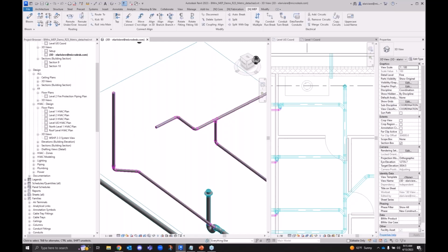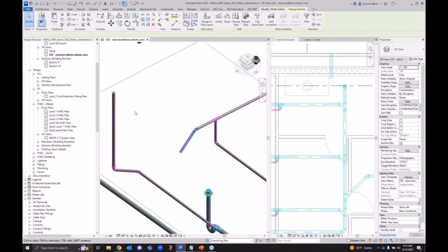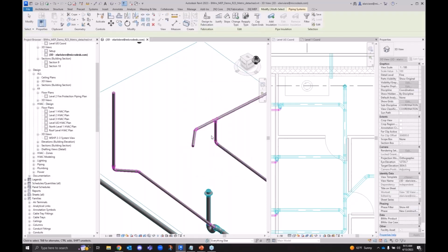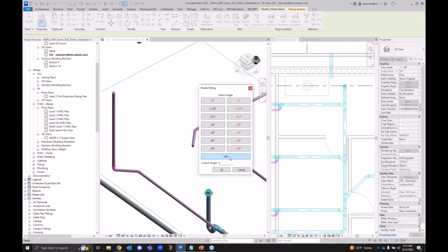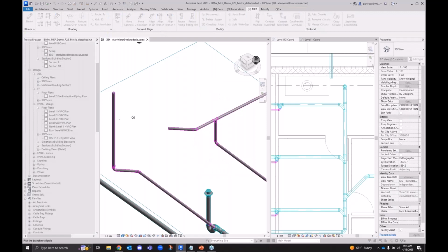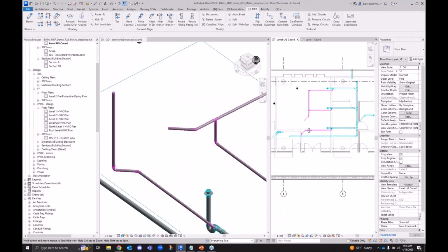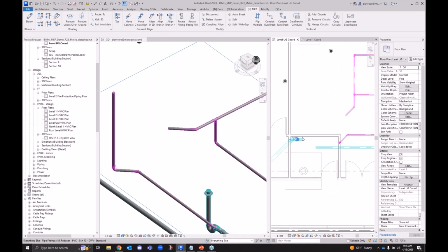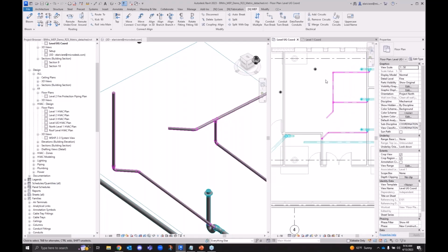Now, I don't want to make it seem too easy, or like we can only do stuff with 90s. If you want to go ahead and use a 45, you can absolutely use one of those elbow 45 commands to drop it in, rotate it up 90, and if you missed, no big deal. We can 180 it the other way. And guess what? That same align branch continues to work as long as we are a little bit closer to the connection we want. Now, I think we may notice that if I tried to make that connection, we will absolutely not be able to.